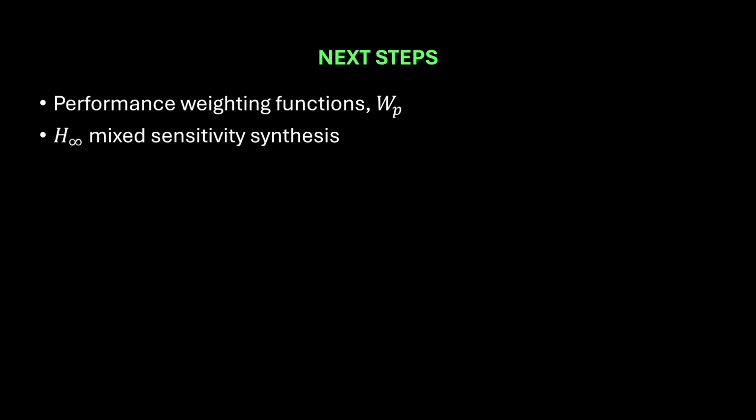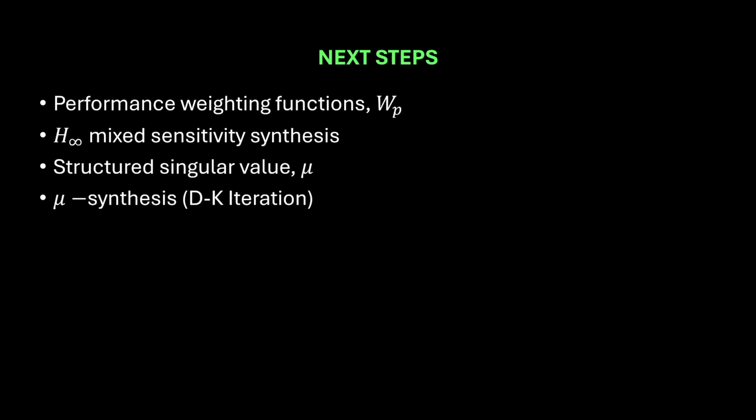Future topics to this lesson include performance weighting functions that can force desired controller behavior. H-infinity synthesis can squeeze the controller to behave like the weighting functions intend. Uncertainties arguably enter in a structured manner. Therefore, for more accurate robustness analysis, the structured singular value mu could be applied. And mu synthesis with the D-K iteration creates controllers that are iteratively optimized for the structured uncertainties, potentially more specific and relevant to our aircraft.